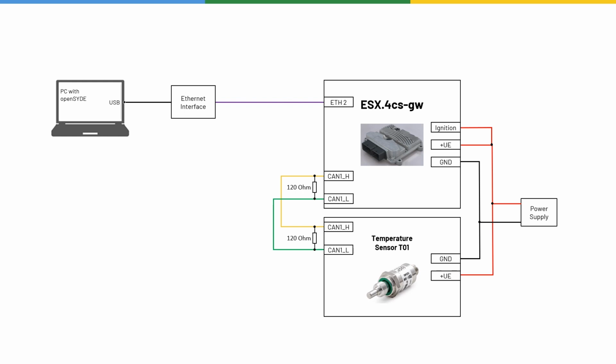To be able to observe the data transmitted between the controller and the sensor on the CAN bus directly with the openSYDE CAN monitor at the end of the video, we connect the PC additionally to this CAN bus via a PCAN USB interface.